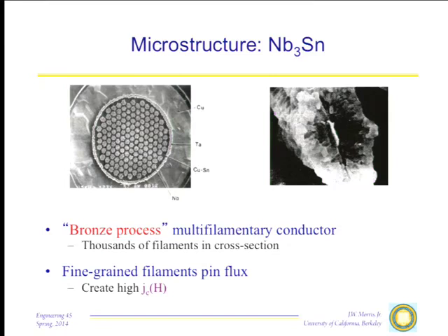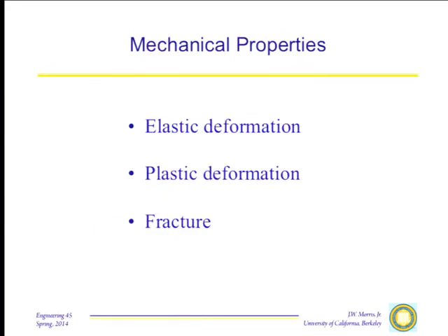And this is kind of the workhorse superconducting wire for the very high field magnets. Ordinary magnets still use niobium-titanium. If you're working on a magnet with an operating field less than about 5 Tesla, you go with niobium-titanium because it's cheaper and easier to manufacture. But that's about all I have time to say on superconductors. Fascinating area, but the engineering importance really hasn't hit. Maybe it will one day, who knows, but it hasn't yet.